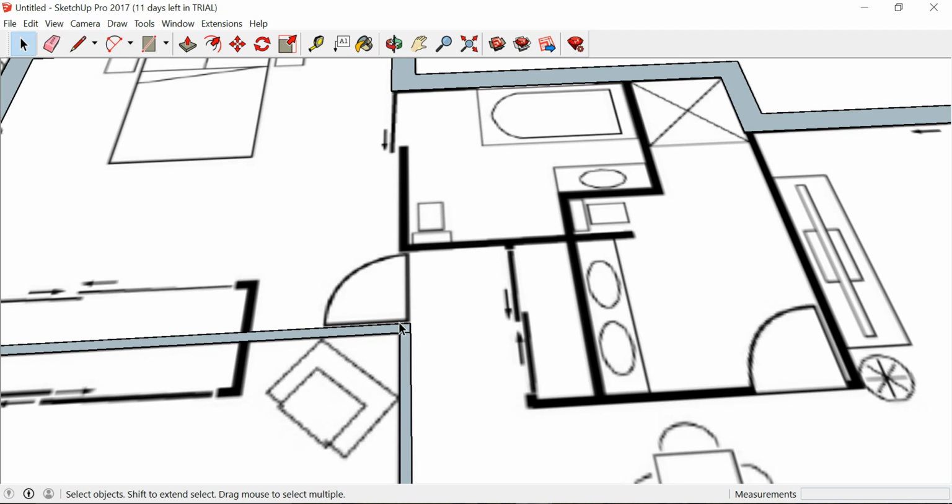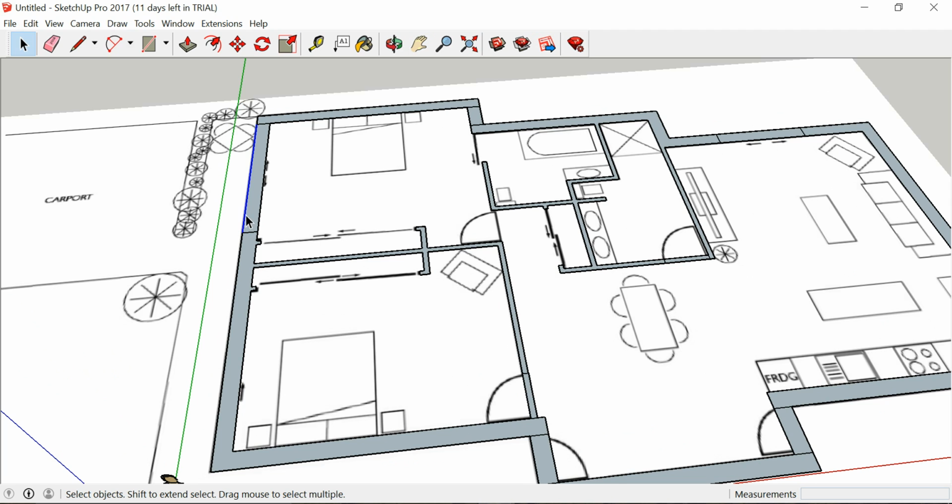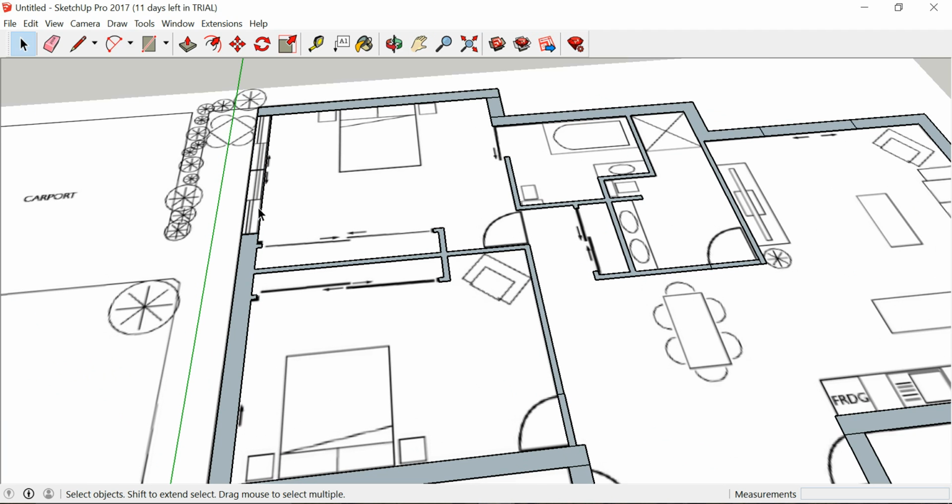And I'll continue to do these exterior walls, and we'll pop back and then we'll start dealing with pulling these walls up. Okay, now we're going to pull the walls up to the correct height, so 2.4 meters is the standard height. I have just included just the little sections of where I want the windows to be and where I want the doors to be around the building.